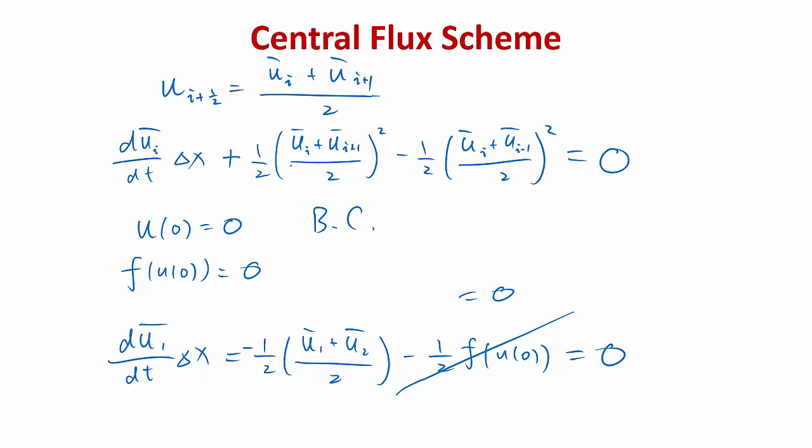All right, so this is the simplest example of finite volume. And I'm going to warn you first, this scheme doesn't work. I mean, it's a perfectly valid finite volume scheme, but for reasons I'm going to tell you in the next lecture, this works only in smooth regions of the solution. It does not work when you have a shock wave.